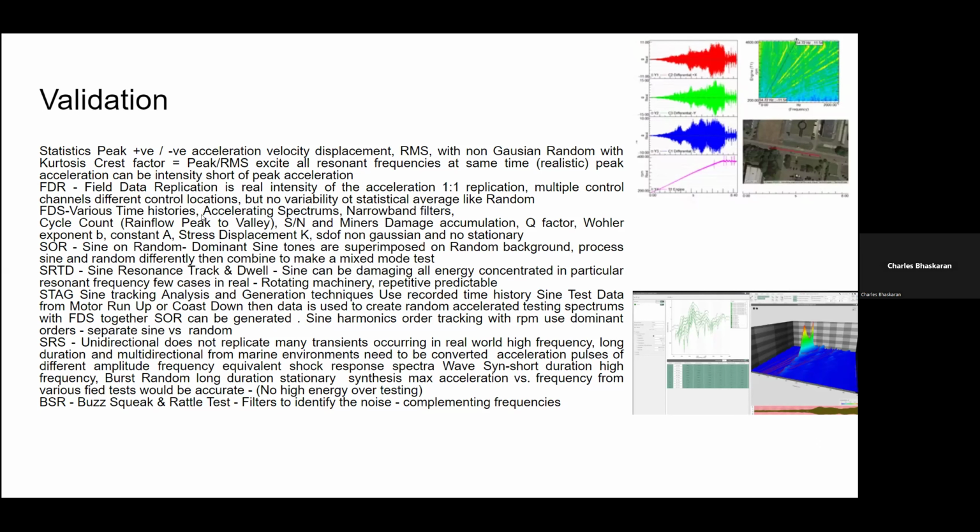Basically, we get a whole bunch of time histories. You just go do your tests, do the S-turn, go cruising, take all of those different conditions, and we put them through these narrowband filters. And we do what's called cycle counting. And there are some rainflow methods that we can use to calculate the peak to valley. And these are going to be your stress amplitudes, right? And then you compare it against the material properties or SN curves or strain life curves.